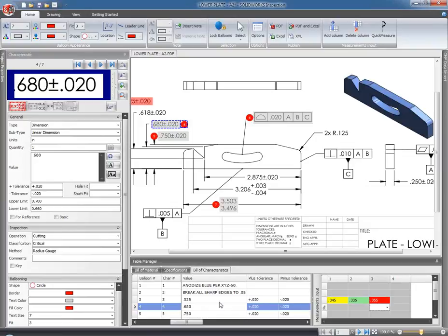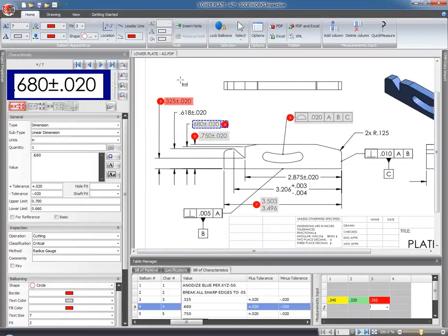And we can simply key those values in for any given one of these characteristics, and additionally create an inspection sheet that illustrates this for us. Notice also in our graphics area that some of these inspection items are taking on the colors associated with that red light, green light logic. And it's always going to show us the worst case scenario based on our project settings.